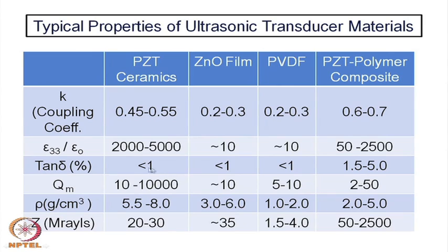the quality factor. The mechanical quality factor Q comes from the high piezoelectric coefficient. So, its piezoelectric coefficient is less, but its density is also low and the dielectric constant is also low, whereas these three values for PZT ceramics or any ceramics for that matter are very high.